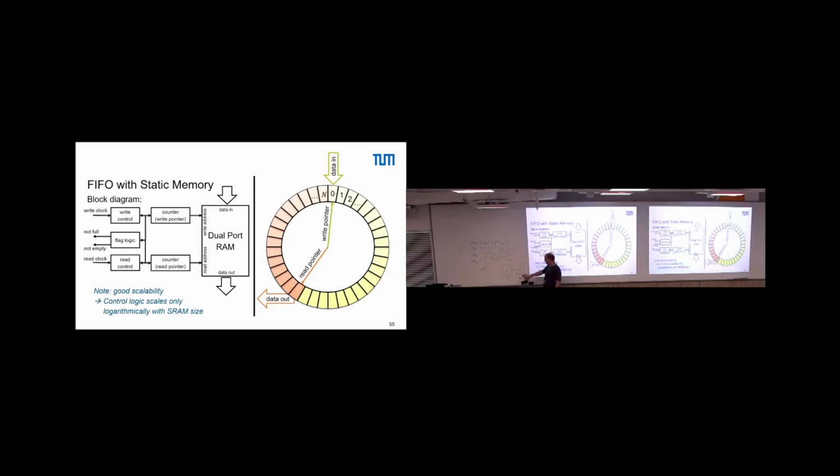The clock that goes here is another one than the clock that goes into this system. So you can synchronize all your flip-flops, all your internal stuff, on clock 2, and perfectly compute all the timing in your circuit, and all is good because you respect your setup and hold times. We are in a kind of perfect world. Now this guy from A comes, also in a perfect world, all synchronized. But now they output something with this clock, and you receive it with a clock that is probably that one.